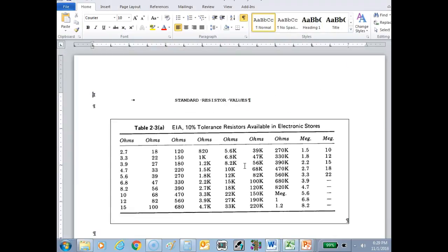This right here prevents me from putting it right in the center. Standard resistors. I've got to choose what? Standard resistors. Right? You understand? And I'm fooling around with a lot of stuff. I'm fooling around with input impedance, output impedance. I'm trying to make it match my previous amplifiers, and I'm trying to do this with what? With resistors that I didn't pick. I got two options. I can use rheostats all over the place, or I can use these resistors that cost less than a penny a piece.